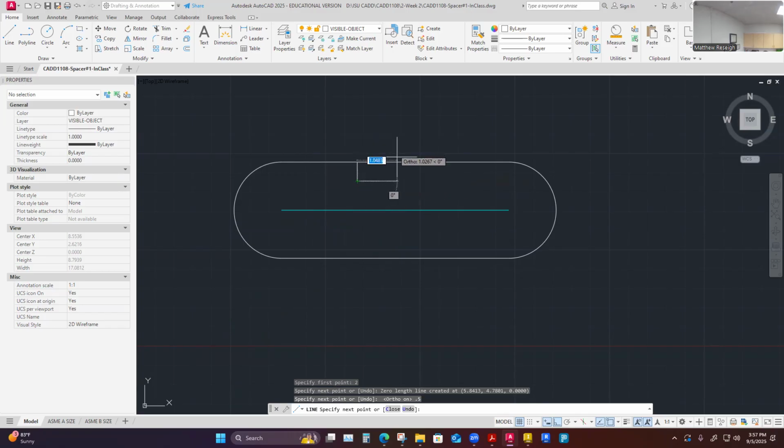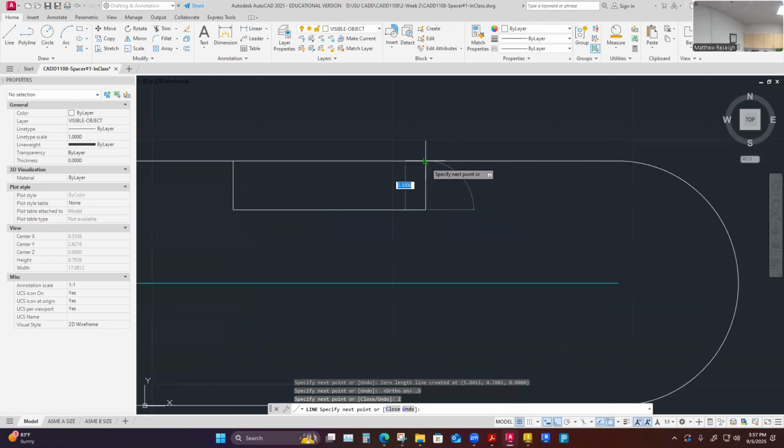And then over here, I'm still in ortho mode. It really helps me draw a nice 90-degree. It's 2 inches over. I'm still in ortho mode. See, it only allows me to do that. So I'm going to just go up here and terminate right there at a perpendicular grip.